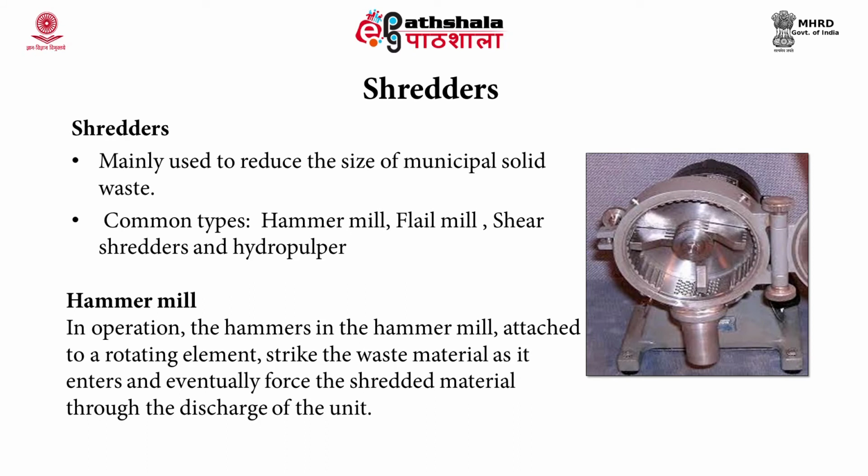The hammer mills are often used in a large scale operation for reducing the size of the waste. It is an impact device and it consists of a number of hammers which is fastened to an inner disc, and the disc rotates at a very high speed. Sufficient hitting results in the crushing and tearing of solid waste. In this way, the size of the waste is reduced.